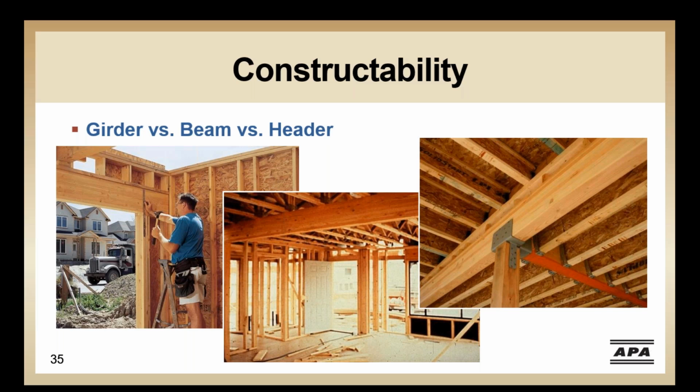Pictured on the right is an LVL beam that frames into a glulam girder. The center photo shows a long span girder. And the photo on the left shows an LVL header being used in a portal frame application, where it extends over the sidewalls. The variety of sizes and strength available with glulam and SCL products allow the specifier to select the right beam for the application.